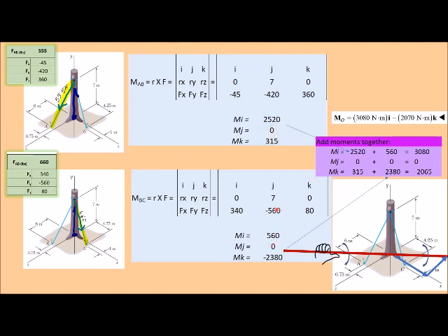And here is the K direction. So when you add these guys together, you get something kind of big in the I direction from AB. You get something kind of big in the K direction from BC. And when you add these two together, here's the overall axis that it's rotating around and the magnitude of how much that tree is getting pulled around this axis. And you're going to use that right-hand rule for positive versus negative. So it's rotating around to the front. That will stick your thumb backwards and add these vectors together just like you'd add a force vector together.